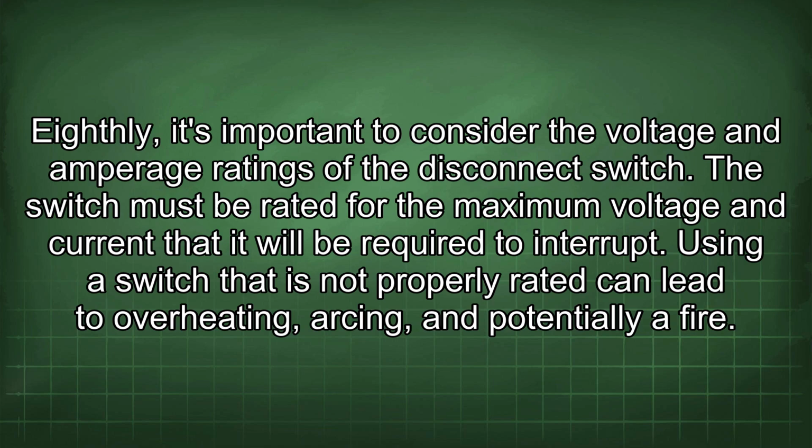Eighthly, it's important to consider the voltage and amperage ratings of the disconnect switch. The switch must be rated for the maximum voltage and current that it will be required to interrupt. Using a switch that is not properly rated can lead to overheating, arcing, and potentially a fire.